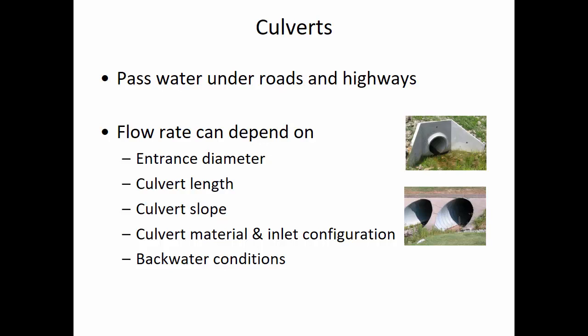They would do the watershed estimation and identify the Q, but then they'd also dip their toe in the hydraulics area and size the culvert as well. And so that's why, even though this is a hydrology class, we're going to do a little bit of hydraulic design, including the culvert software that we're going to demonstrate today.